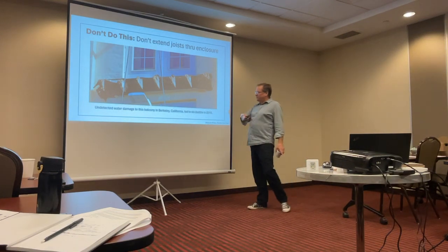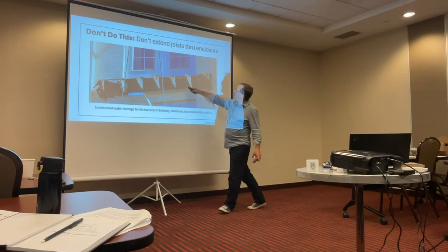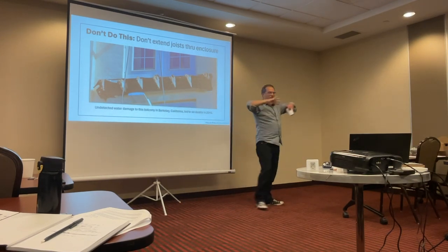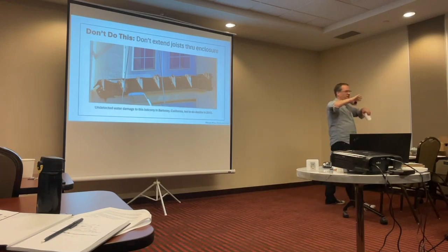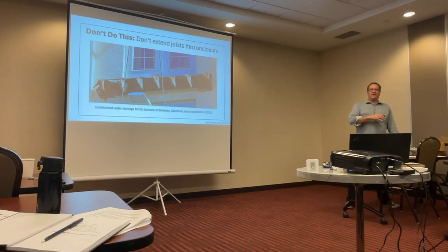And we've seen, this is from Berkeley, California, this is kind of a famous fail where the conventional wood coming through the building rots right there, because that's where all the moisture is coming and going and coming and going and coming and going. And over time, you have 5, 6 people on that thing, and boom, down it goes. So not only is it awful thermal bridging, but it's pretty unsafe practice. And as summers get hotter and winters stay just as cold, the degradation cycle of exposed timber will be faster.